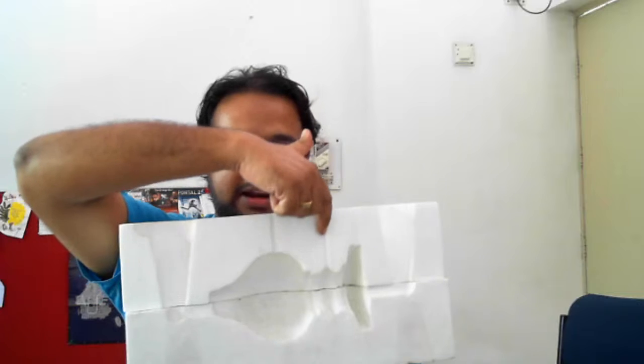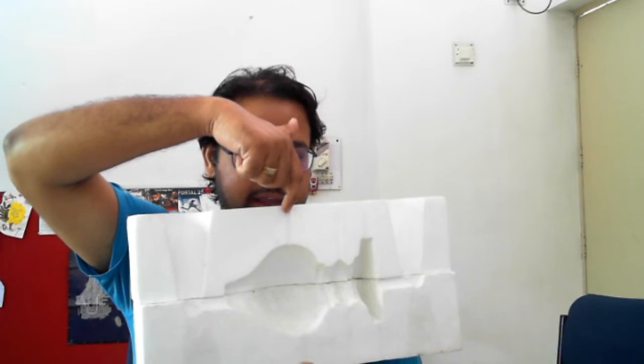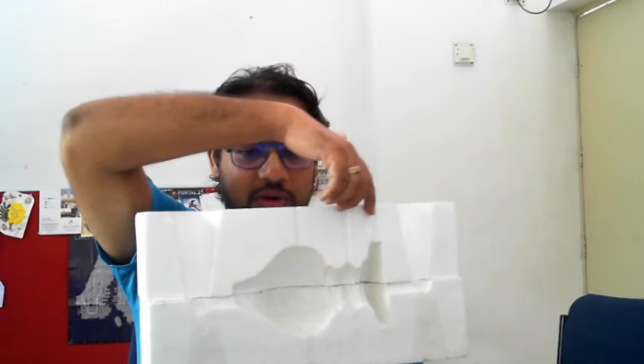These vents go up to the top. And then you have two places. This is the pouring basin. You can see there's a small basin here. And this is the sprue. I think it's a larger sprue because she wanted this to be the riser itself. This goes down. There's a small place where it catches the material, and there's the gate, and it flows into the material.